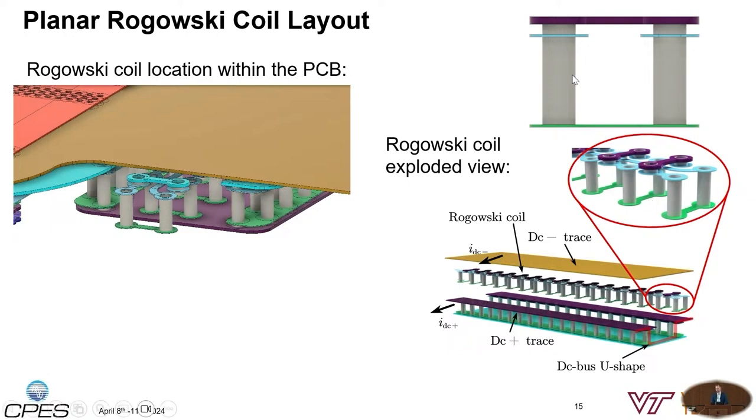And the winding itself, depicted in the top right, is created with vias, where the right part of the winding is created with a vertical via. We go forward slightly, as we have limitations in space, and then go up with a laser drilled via. So that creates the right vertical structure of the Rogowski coil winding.